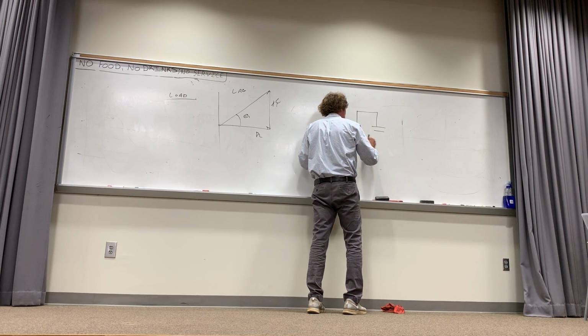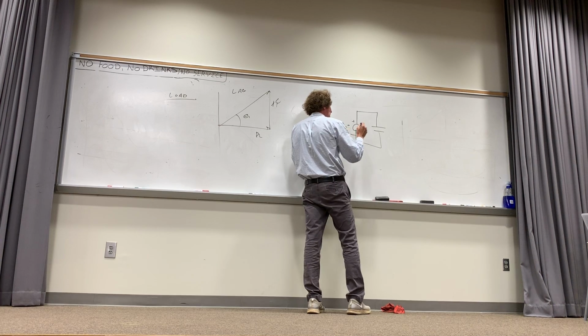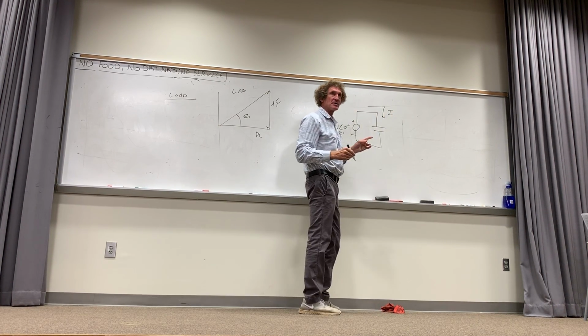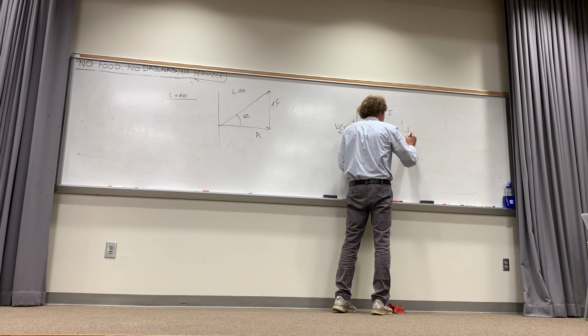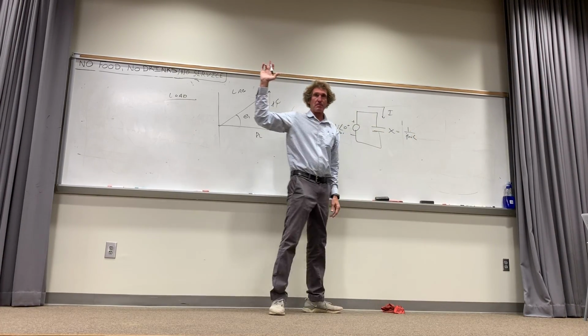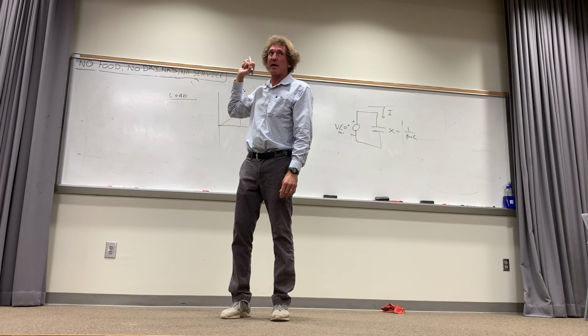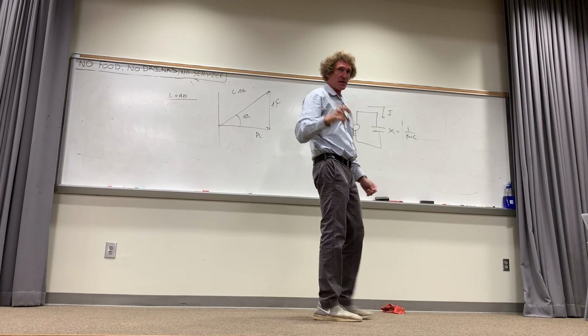and I have a voltage here, I'm just going to call this voltage V, just V at 0 degrees, and assume this is RMS. Well, that's going to give a current here, I. And if you remember the actual reactance of this capacitor is 1 over j omega C. How many remember that? The capacitive reactance is 1 over j omega C. That's in ohms. The inductive reactance of an inductor is j omega L, right? These are things that are common. You've had many, many times probably in physics, and you've had it here.